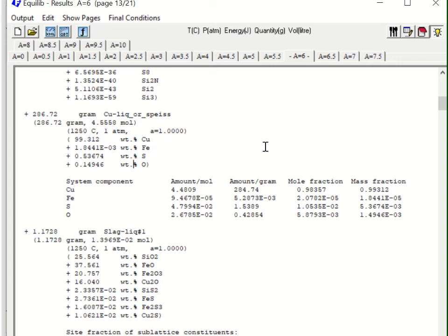So this shows you briefly how we can use the FactSage calculation for the roasting process, then the smelting process, and the converting process. One of the keys you have to think about in this kind of calculation is saving the output as a stream and then entering it into the next one as input. So that's the key to make this flowsheet type of calculation. And also, in terms of research, while you are doing this kind of calculation, you see that different flux amounts change your calculation result.